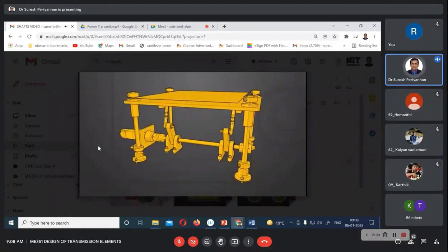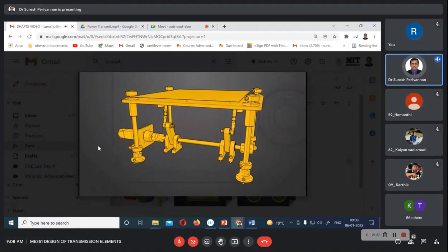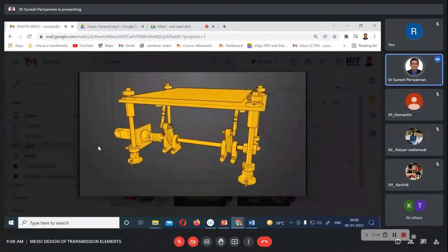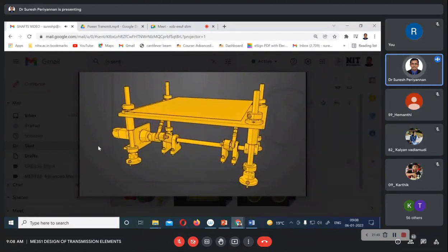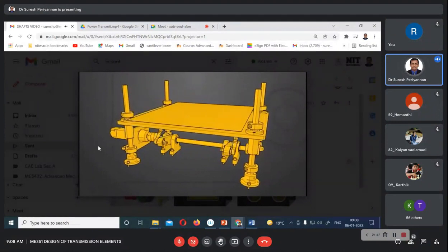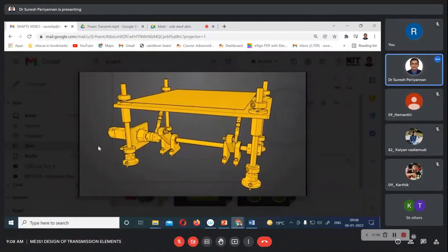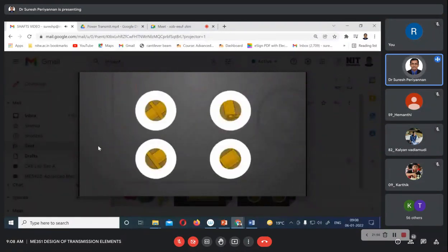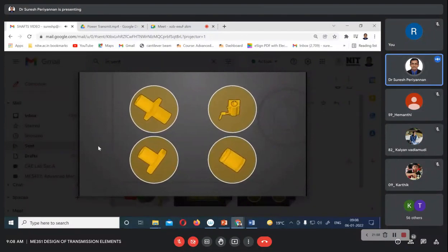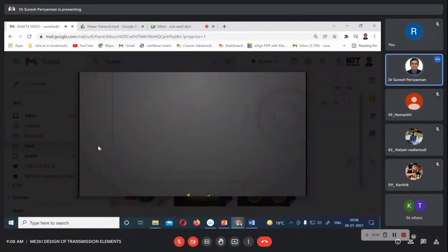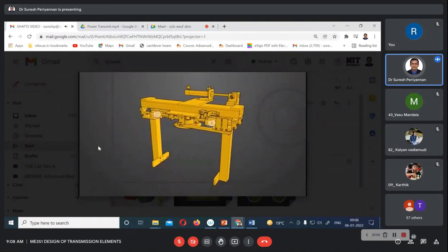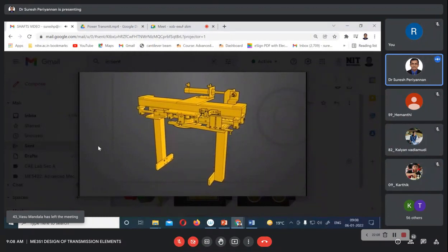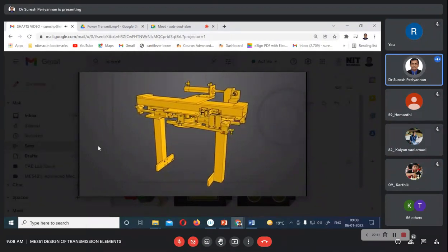Along with a vast selection of linear shafts, Masumi offers complementary accessories to provide a full solution. In this example, a workpiece is lifted in order to transition to the next station. 4 linear bushings with rolling elements ride along the linear shaft to provide a smooth, low-friction guide throughout the entire stroke. These bushings are offered in many shapes and sizes to accommodate your requirements. Here we can see the pillow block bushing is chosen due to the mounting orientation. As the bushings actuate toward each other, the workpiece guide centers the unit on the conveyor.